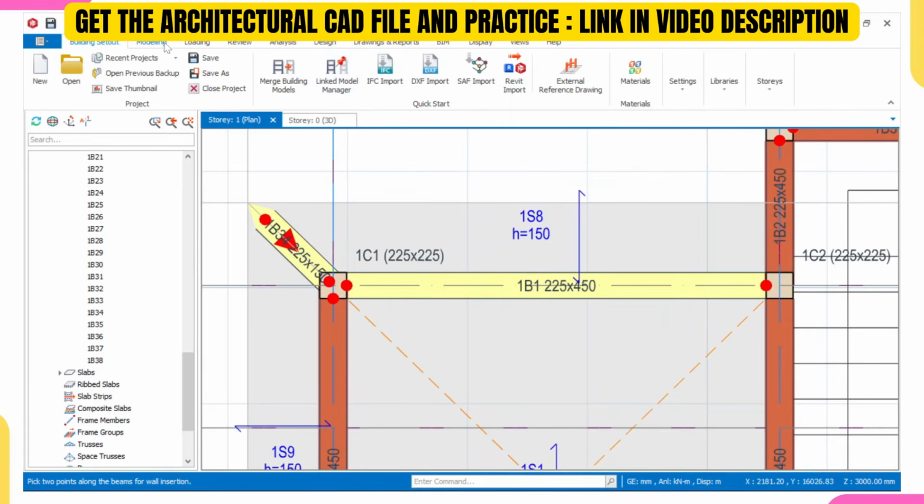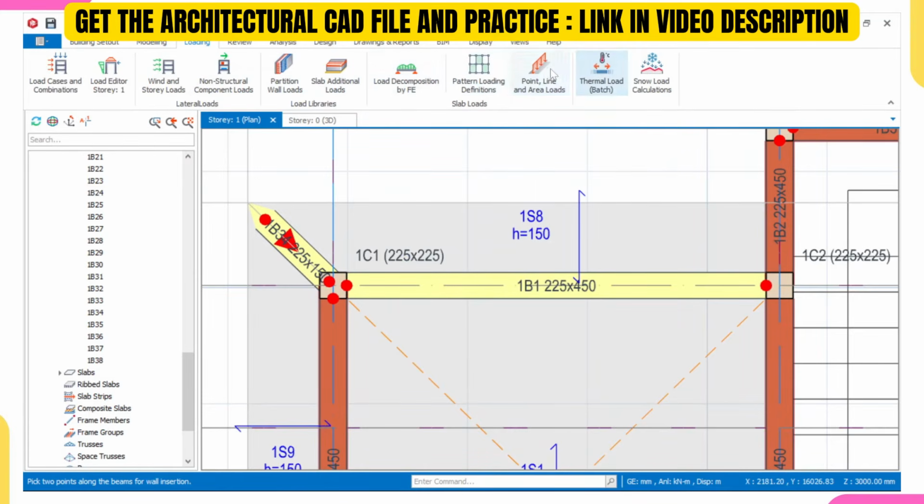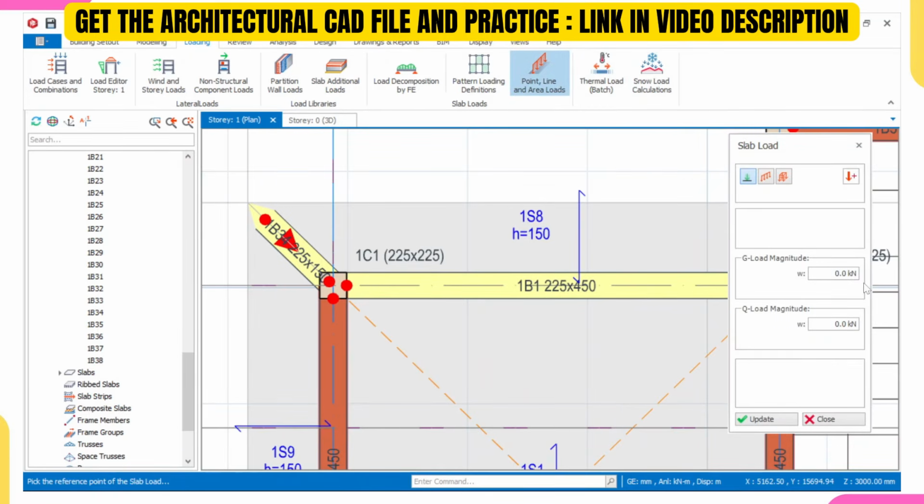Then I'll come over to modeling, then loading. Look at point load, line load, and area load. I'll click on it and come over to line load. Then come over to this magnitude. This will be a dead load, so I will be using this dead load. This one is for live load. This block wall is not live load because it is not movable. It will be there forever. So it is dead load. So I'll be using 9.4 as the load magnitude.